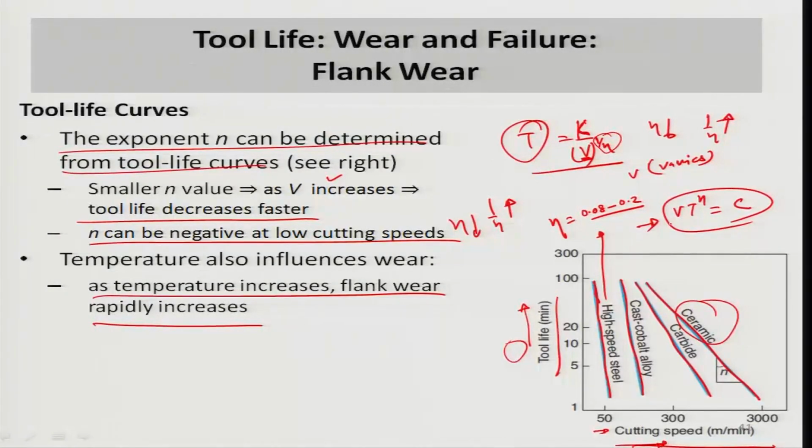This equation is particularly significant when we talk about machining conditions and optimum machining conditions, used to find out the overall cost of the machining process or overall time in the machining process. And this particularly holds true for NC and CNC systems, where there are many such inserts and there is a tendency of the inserts to be repeatedly worn out because of high speed machining processes, and you have to either grind them or increase the sharpness of these tools before reuse.